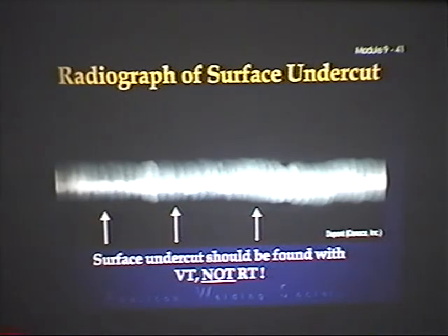Technique's big. If you're running too hot, using too long an arc length, moving too fast, all of those things can contribute to undercutting. On page 212, it gives us some reasons. It says excessive welding current, incorrect electrode manipulation, using an incorrect welding rod which provides filler metal of the wrong composition. You could be using the wrong type of rod. Your electrode angle is too small. Your arc length is too long. Your welding speed is too slow. Or you're using wet electrodes. All of those are reasons that you can get undercut.